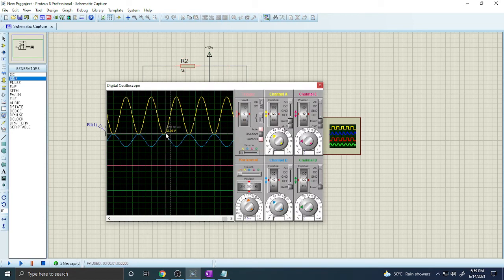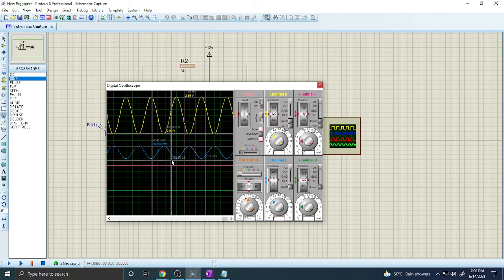This is 3 times. Now this is minus 2.9 volt to plus approximately 2.95, that is equivalent to 3 volt. And the lower part is minus 950 millivolt, that is equal to about 1 volt. This line is used to vary the position of the signal on the screen. Now the input amplitude is approximately 900 millivolt, about 1 volt. If the input is 900 millivolt, multiplied by 3, that is approximately 2.9 volt, or equivalently 3 volt.